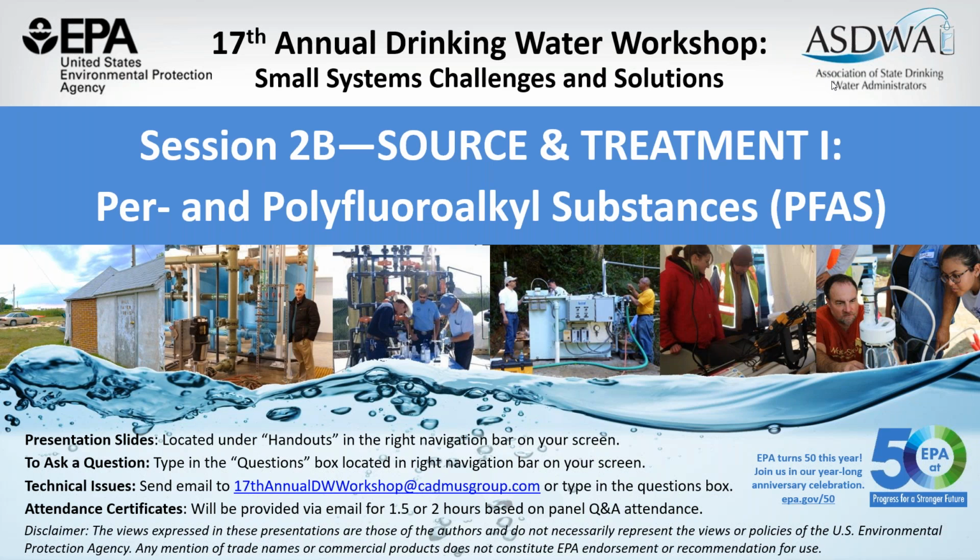You try to minimize the backwashes that you're going to use with carbon contactors anyway, because you don't want to be affecting the shape of the carbon. So usually if you can go a year, that's kind of your gold standard. You're going to go for a year before you have to do a backwash. There were no head loss issues that would have triggered a backwash for this system. So to my knowledge, there were none between change outs.